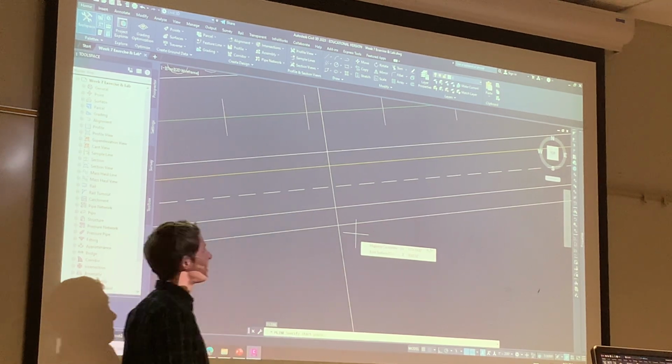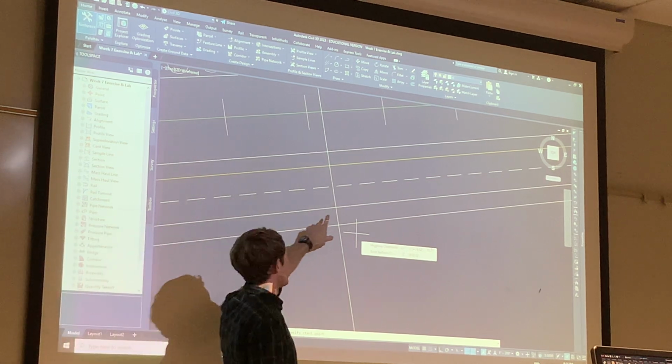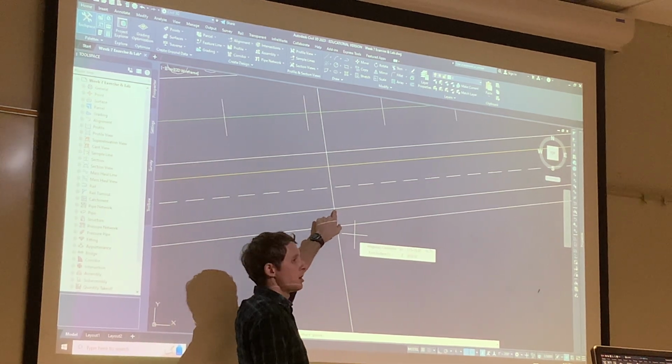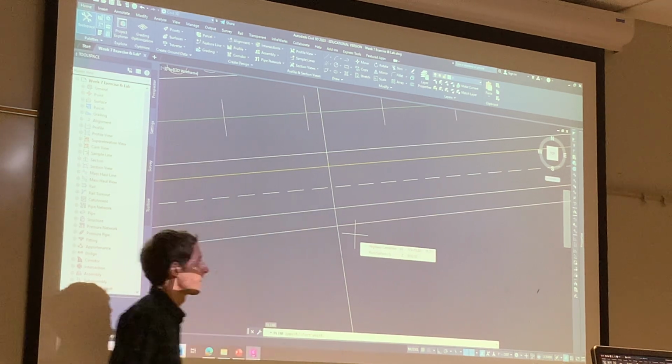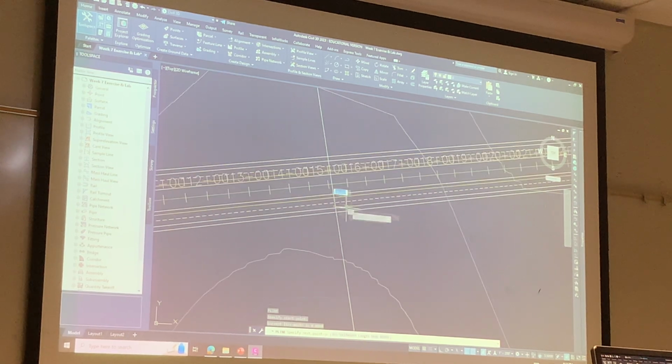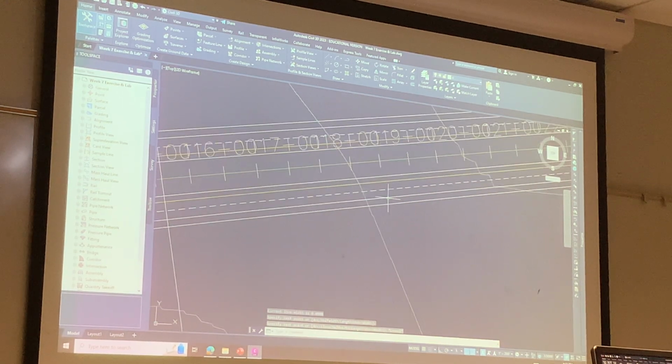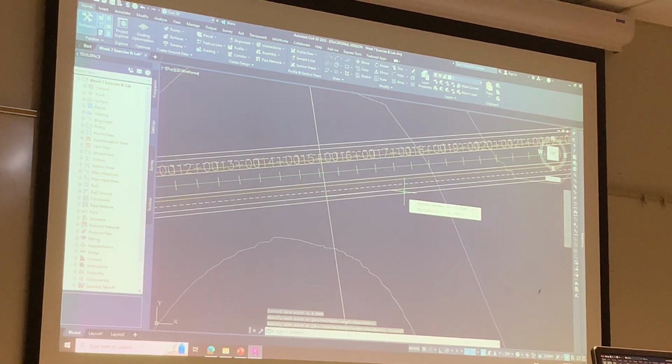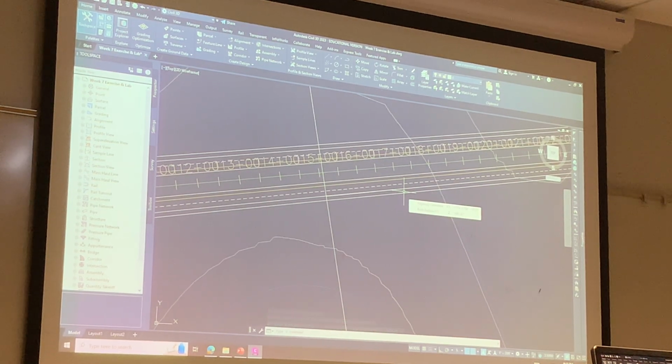Yep. So what I'm gonna do is start my line from this point. This point is gonna become the nose of my off ramp. So start there and I will trace it. Now, you can only trace it if you're drawing it on a tangent. If that offset is on a curve, you've got a lot more complication. It's a lot more complication that can be dealt with, but why put yourself through that trouble?